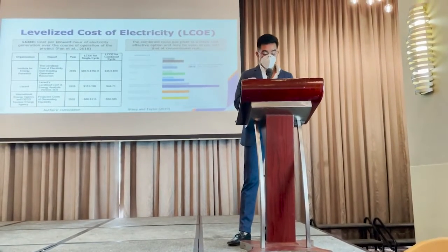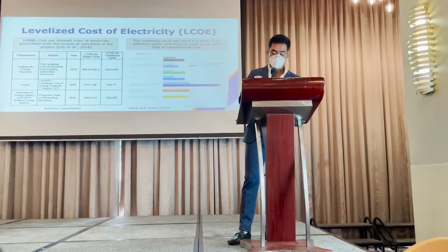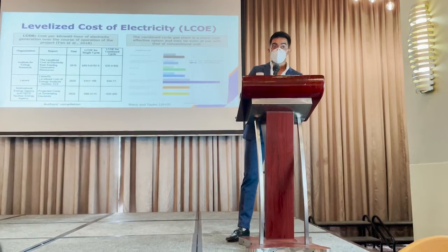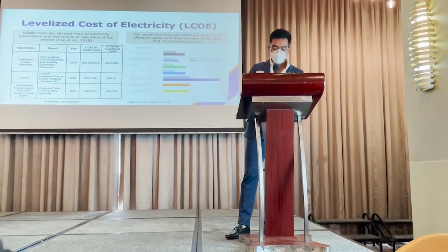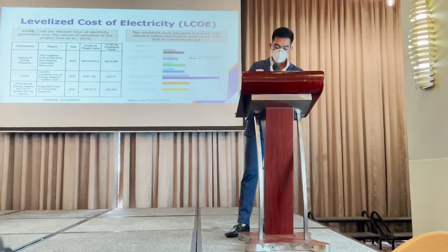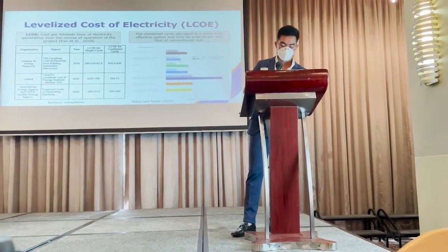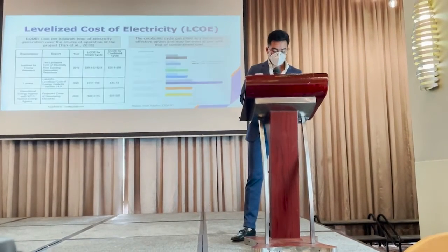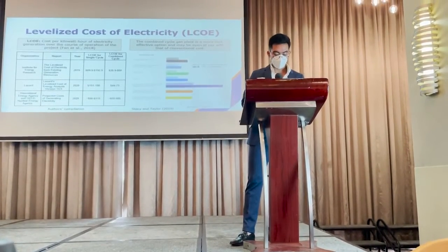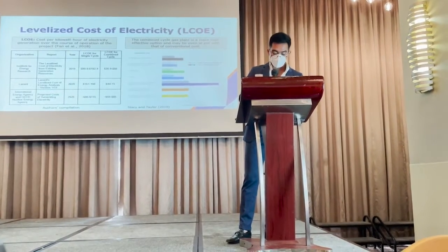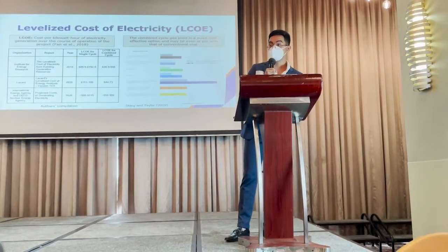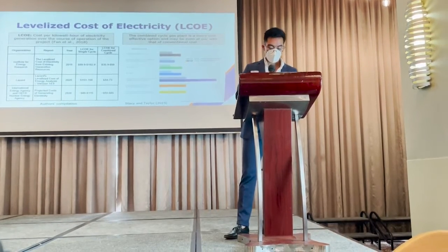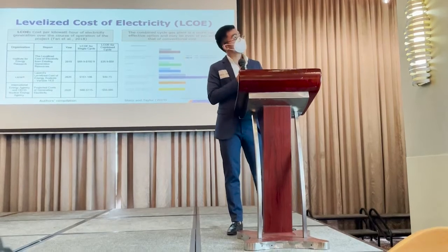We also reviewed literature on levelized costs of electricity of single cycle and combined cycle power plants. The levelized cost of electricity, or LCOE, is a cost per kilowatt hour of electricity generation over the course of operation of the project. We can use this metric to compare various electricity generating technologies of different capacity factors, economic life, fuel costs, and capital cost. We show here a table comparing LCOE values from different organizations.